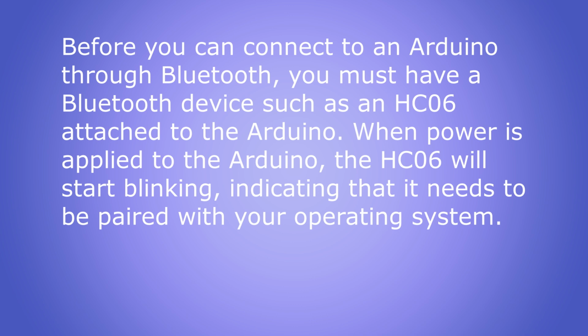Before you can connect to an Arduino through Bluetooth, you must have a Bluetooth device such as an HC06 attached to the Arduino. When power is applied to the Arduino, the HC06 will start blinking, indicating that it needs to be paired with your operating system.